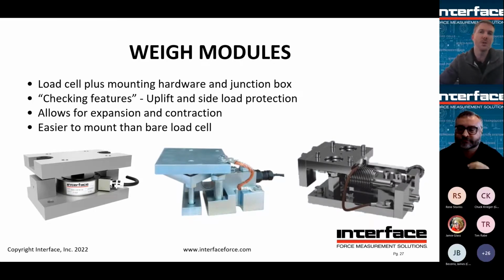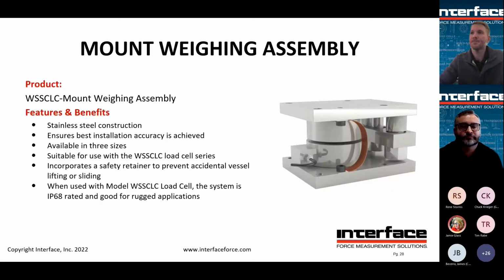Some will hold up better to shock loading. Some are better for mixers. Some are better for high accuracy. They all typically have some of the same features as far as uplift and side load protection. A lot of them will allow for thermal expansion and contraction and make it a lot easier than mounting a bare load cell. Next slide.